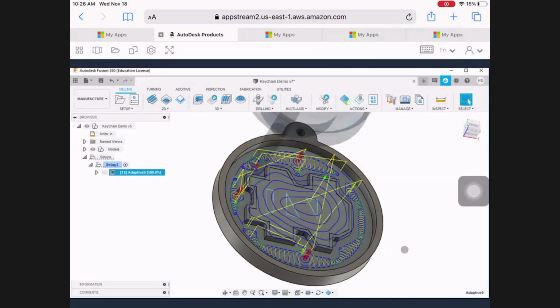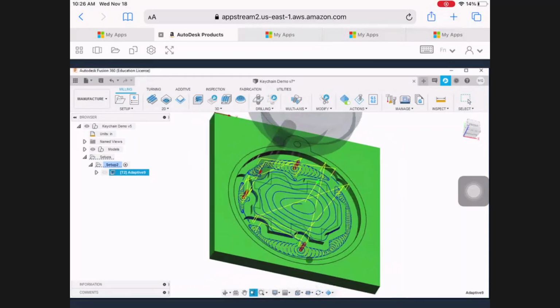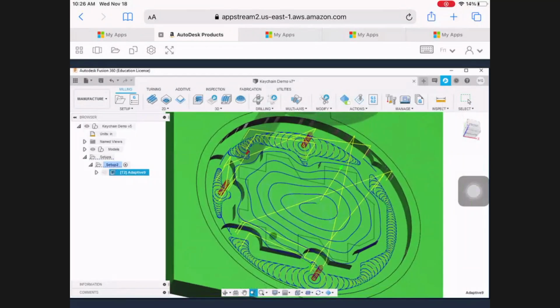So what you see is this. It's the result of the toolpath, which is our helical entry. So you can see the helical shape with a 0.05 diameter, and then the 8-degree angle, which is the angle of like the coil spring coming down. That's how it can safely enter the material. And then all of these passes have been created from all those settings that were in those windows. So that's your first adaptive toolpath.